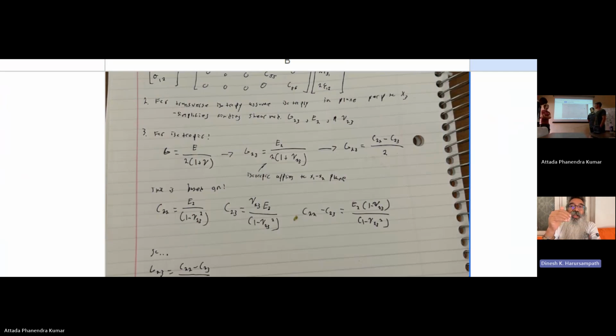So make sure that you are aware of which particular stress measure number or strain measure number you're talking about. Same thing with the displacement and the forces. Don't just say F or M. Talk about F1, F2, F3 or M1, M2, M3. Similarly, U1, U2, U3 and the rotations as phi1, phi2, phi3 to avoid confusion with theta, which we use for the independent variables r, theta, z, cylindrical coordinates.